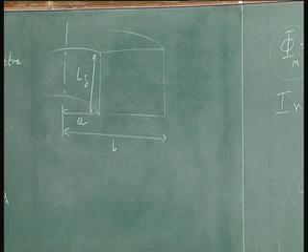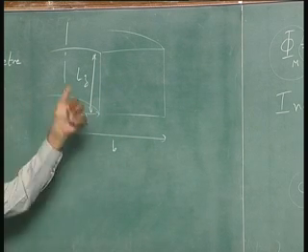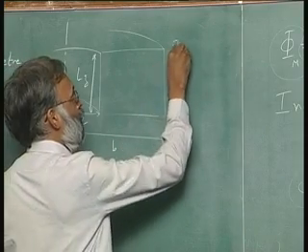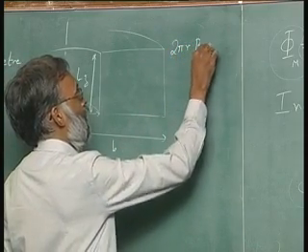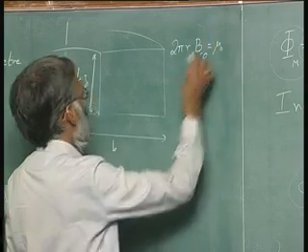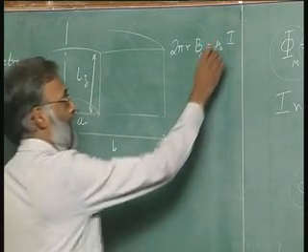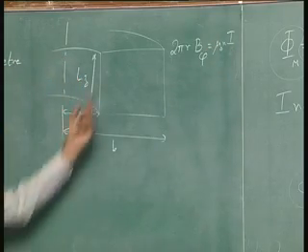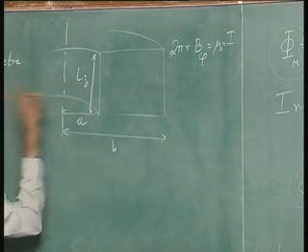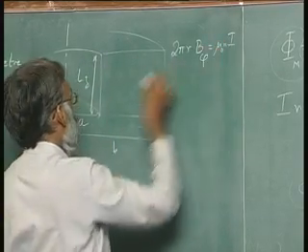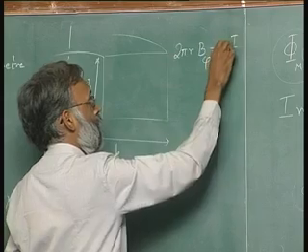We worked out that if you take this solenoid, the magnetic field is purely in the phi direction. Therefore, you can apply Stokes theorem and say 2 pi r B phi equals mu naught I. But there are N turns, so I put an N, because when it goes round, all these currents are coming out. So, the number of turns is the total number, mu naught capital N I.